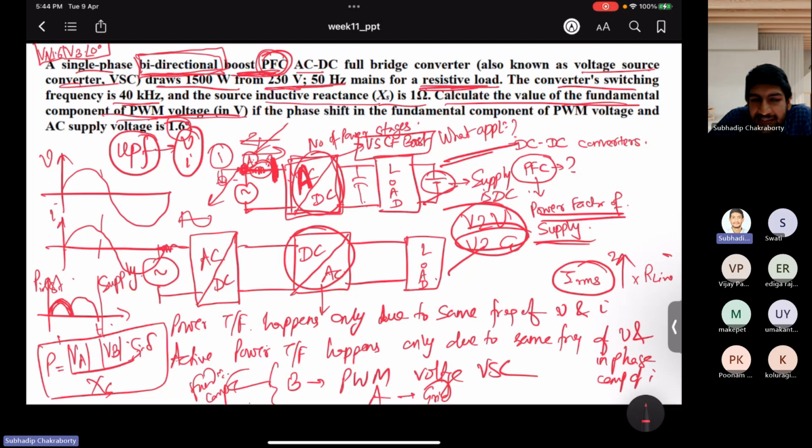In power systems books, they explain well why the active power transfer should happen from higher delta to lower delta. So always the power transfer is linked to the delta, the voltage phase angle. The bus or node which has the higher voltage phase angle will transfer the active power to the bus with the lower voltage angle, which is lagging compared to that voltage. So which one of these two points has higher delta or lower delta? Because if this is bidirectional, we can generate higher or lower delta voltages at point B, because point B voltage is in our control.